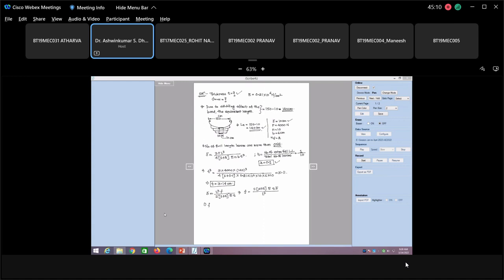So from here F comes out to be, चलो इसका वैल्यू रखो 2 in bracket 2 plus 0.1, E का वैल्यू उसने सेंटीमीटर में दिया हुआ है 0.21 into 10⁻⁶। अभी thickness का वैल्यू हमने निकाला है 3.14 और डेल्टा का वैल्यू उसने दिया है 10 सेंटीमीटर, effective length है 140 का square। तो सर ये इसका वैल्यू आप calculate करके बताइएगा कि कितना आता है। तो 1413, so 1413 newton per centimeter square, बराबर है ना सर ये वैल्यू?